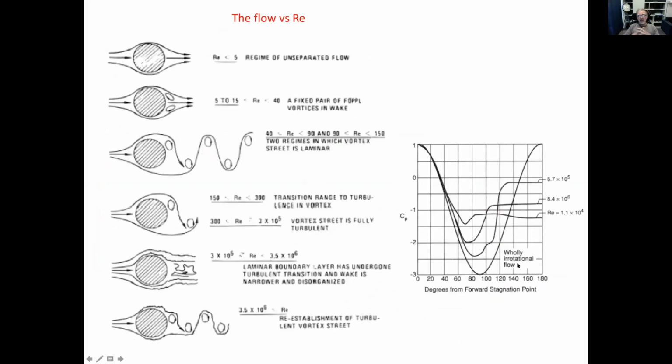Okay, so now let's look at that in the range of Reynolds number. So what I told you is high Reynolds number, but let's just look at that more carefully. So we take a cylinder and put it in oil, very greasy oil, let's say Reynolds number is less than 5, so it's pretty viscous oil, then the streamlines are going to be amazingly close to what we got, very close, but for the wrong reason, because that's a viscous flow.